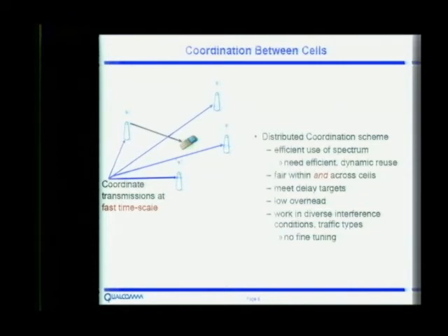So when you talk about the interference management of the macro cell with the femto cells, again the macro cell has to coordinate with these cells to do what? We won't talk about it, but in some sense it's easier because you get some statistical multiplexing at the macro cell and among the macro cells. So you only need to coordinate when femtos can transmit, when a macro cluster of femtos can transmit, and when a macro can transmit.